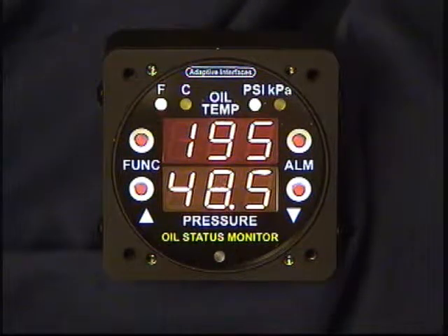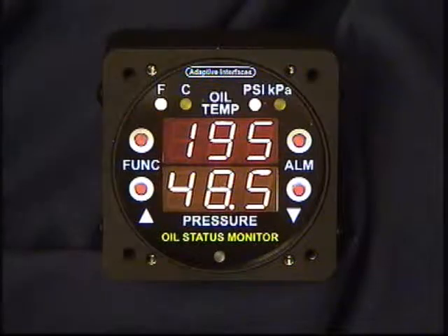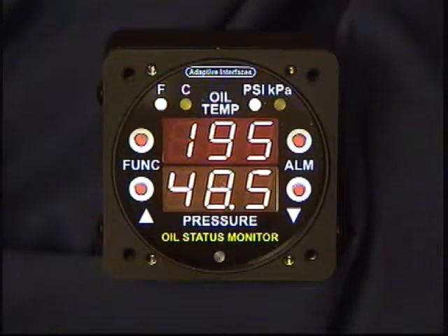The third menu level is a set of calibration data points, and we'll go ahead and get into that. And that is what allows the user to use many different types of pressure and temperature sensors. To use those, all you have to know is two temperatures and the value of the sensor, two pressures and the value of the sensor at those pressures. And we'll show kind of how to get into that and how that works.